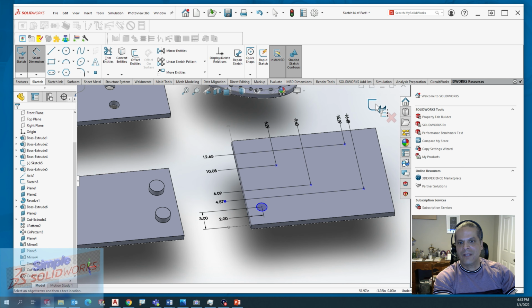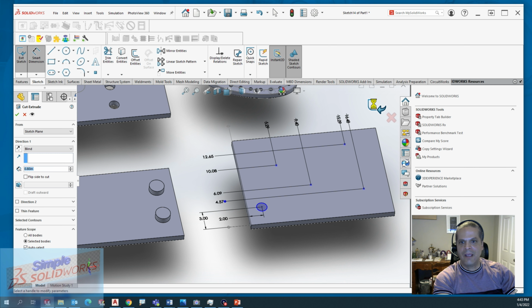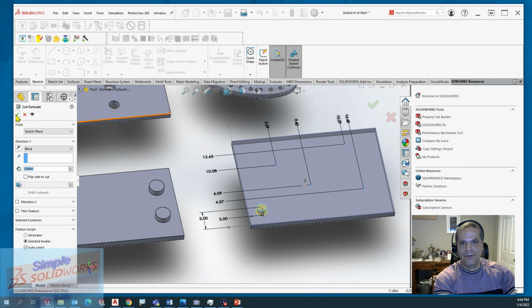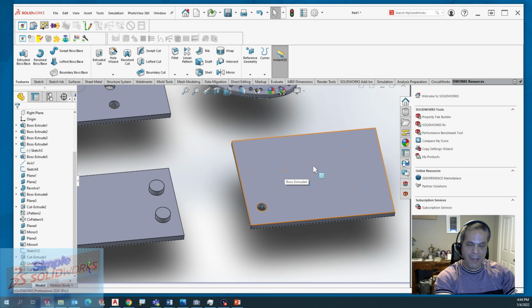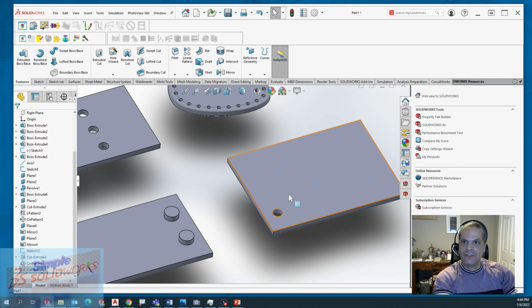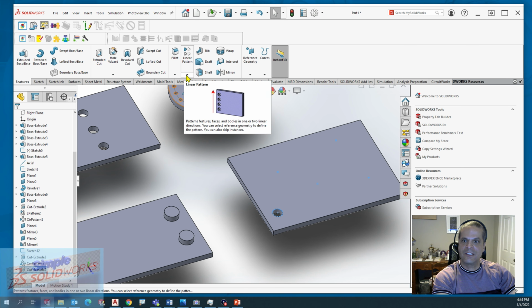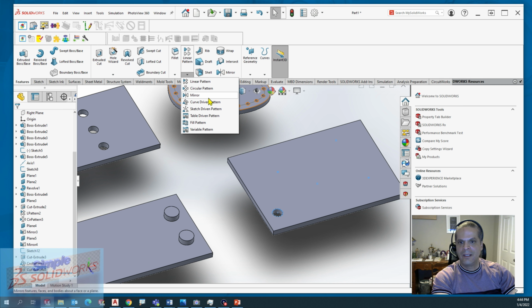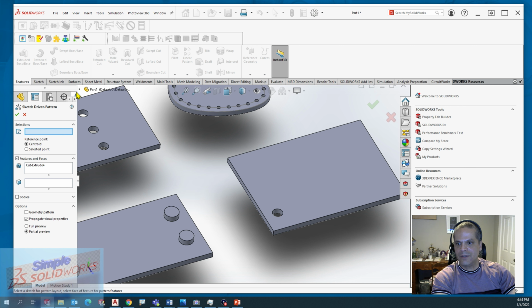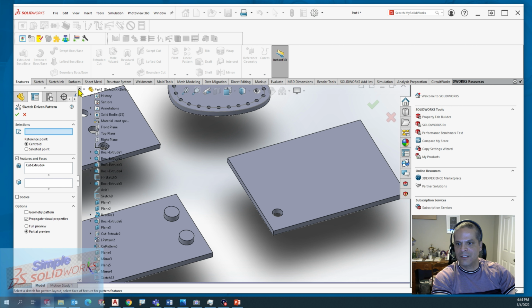So now you just have your extrusion cut. You have your sketch already pre-made, right? You know where you want those next patterns to go. So what you do now is you click on this item here, the sketch-driven pattern. You're going to dig here for the sketch itself. So you dig in there and you find that sketch.